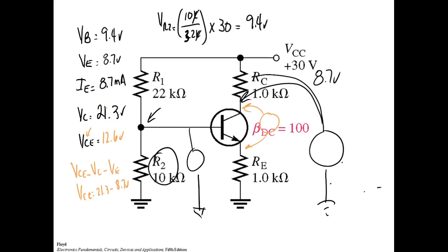So what would be the gain of this? This guy here wouldn't have a voltage gain. It has a gain of 1. So if I put 1 volt peak to peak in, I get 1 volt peak to peak out. We don't know the current gain because we don't know what load we're going to feed this into.